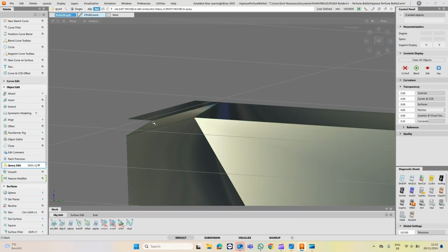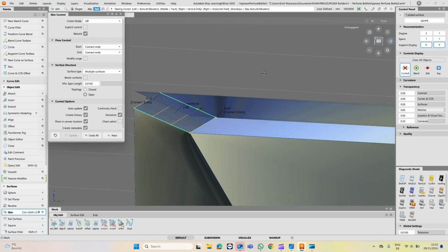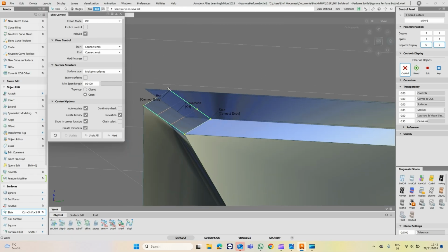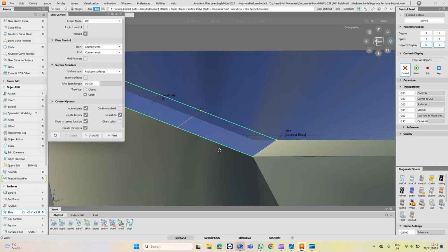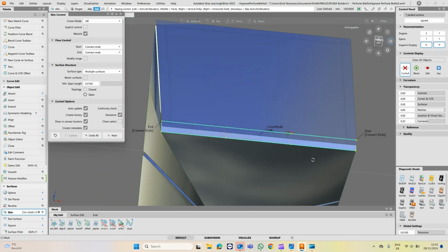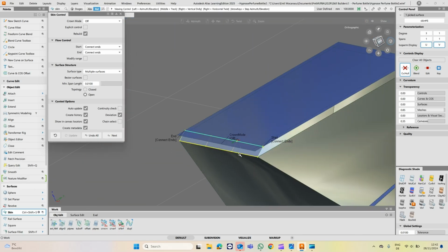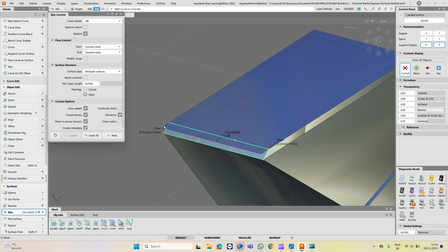We can add some little crown to it. Now the reason why I was looking at that is normally when we build curved surfaces, curves on surface, the CV layout is jumbled up, so you don't get this nice even distribution. And here we get it because we've got simple shapes. Once you've got more curved shapes, that's when it starts going wrong.